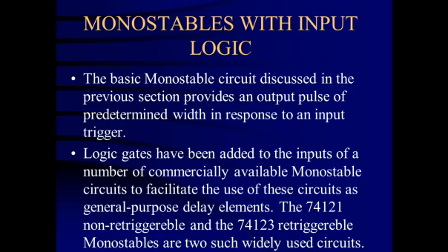Now, sometimes it is required that the circuit should be positive edge triggered also, or negative edge triggered also. In some applications, we require that when the trigger pulse changes from low to high, the circuit should be triggered, or when it changes from high to low, the circuit should be triggered. For that purpose, prior to the trigger terminal, certain logic gates are utilized, and that way the possibility of positive trigger or negative trigger can be derived. This is available in these two ICs.